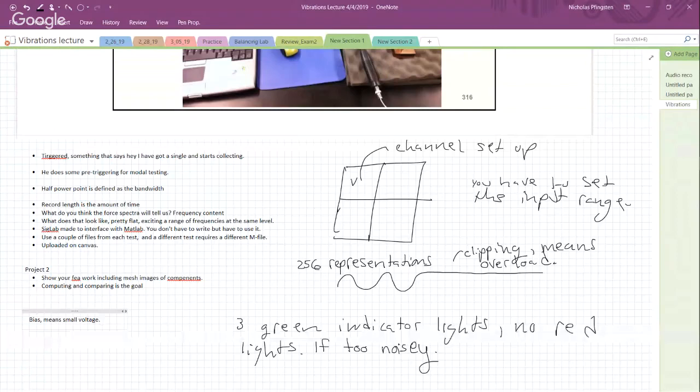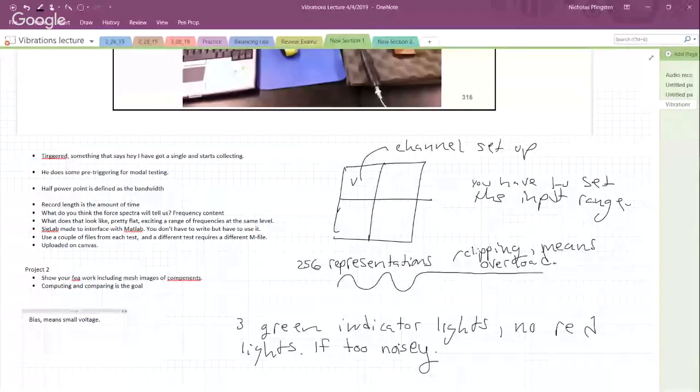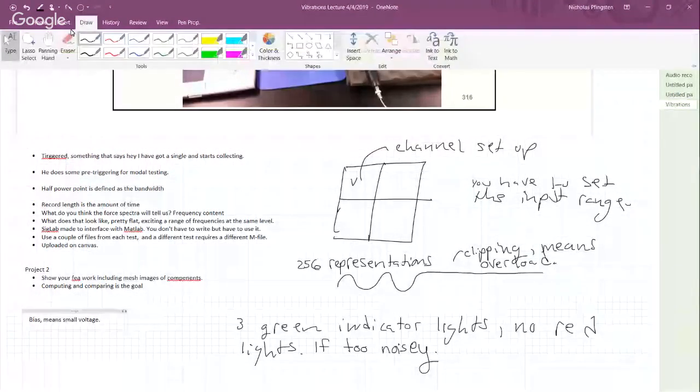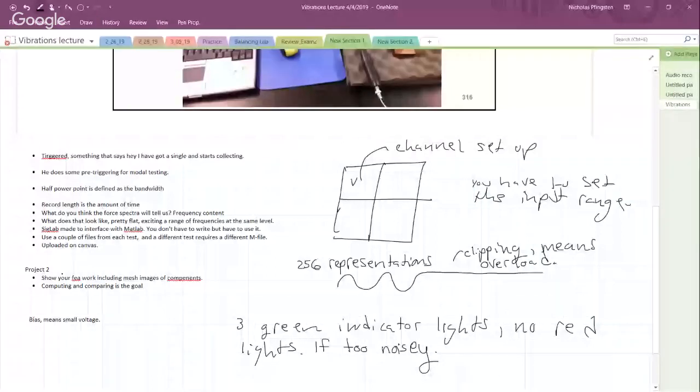So what would the signal be without the built-in electronics? Remember we're talking about a piezoelectric stack? Picovolts. So the built-in electronics are changing it from a charge. Remember pico? How big is pico? 10 to the negative 12. Small. So pico is very, very small. So a picocoulomb level signal is what we're getting. The internal electronics convert that to a millivolt level signal. It's very important to be able to do that.